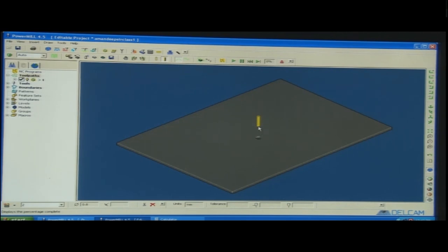Once it has done the machining or some of its operation here, it will come back to the safe height, that is 5 mm. It is going in 2 steps. Because it is rapid mode, it comes 3 mm, then 2 mm again. See it again carefully. It is 5 mm above in rapid mode, now 3 mm down and 2 mm down in 2 steps. Now, in the rapid mode.